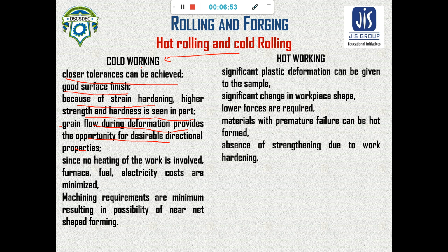Next, since no heating is involved in the work, fuel cost, furnace cost, or electricity cost are minimized. So cold working is somewhat economical. And post-working machining requirements are very minimal, so it results in near net shape forming. So these are the advantages of cold working.